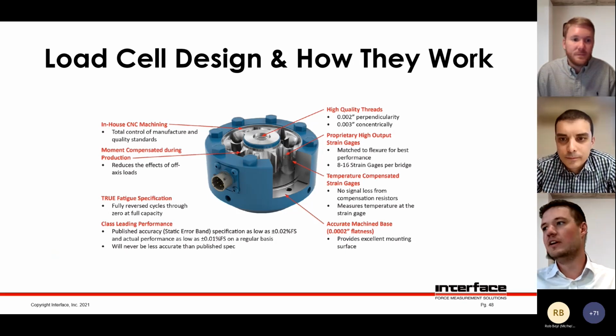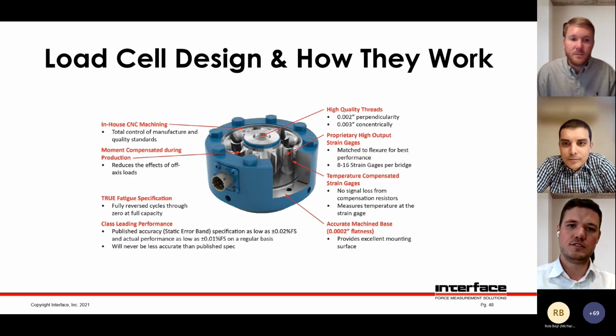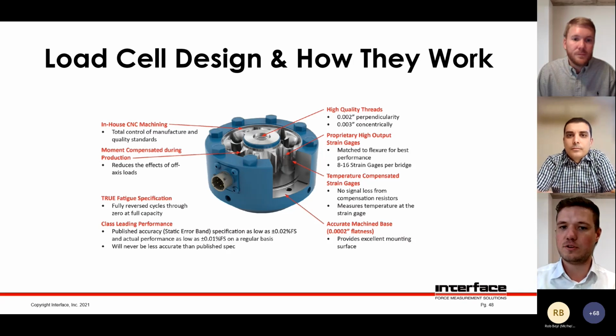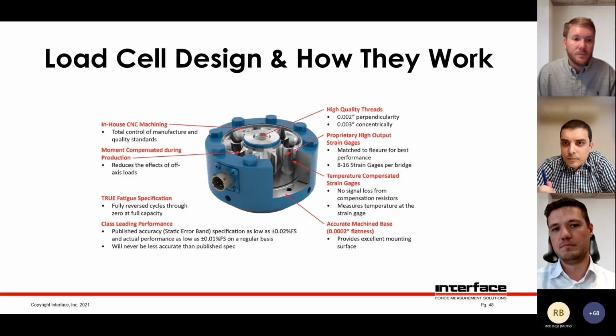Sure. This is a great image of a cutaway of a low-profile load cell, so you can see some of the complex machining that goes on in making one of these. The great thing about Interface's in-house machining is that everything's under control, everything's quality controlled in-house. It means a lot of consistency across different load cell types. You can see there we've got moment compensation during production. The way the flexure is shaped, it compensates for moments naturally. If they are fatigue-rated load cells, they're truly fatigue rated.